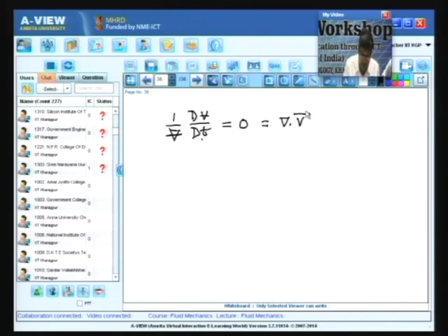I just mention this in this context to avoid any confusion about the incompressibility of the flow. A flow will be considered incompressible when its rate of volumetric dilation from the kinematic condition becomes 0, which equals the divergence of the velocity vector, where V is the velocity field. For a constant density flow also, this is 0, which will be explained again.